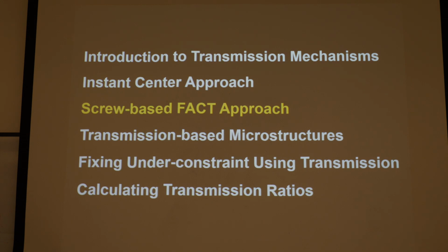Okay, so that's a cool little way to design things, first of all, to design planar things. It's limited to planar. It's also limited to inputs and outputs that are translations at different locations. And it's just going to be kind of approximate, right? Because it assumes all kinds of ideal things. You're not going to get exact things, but it'll get you in the ballpark pretty nicely, okay? And it's a clever little approach, okay? But all your designs will look like a bunch of bodies with instance centers and stuff, okay? But that's okay, right?